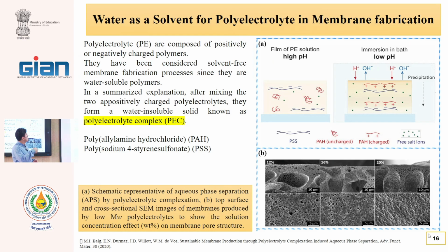These polyelectrolytes are mostly used in the coagulation process in water treatment, for increasing the precipitation of iron or aluminum in the coagulation bath in wastewater. We add one positive polyelectrolyte and one negative polyelectrolyte, and we have a solution.